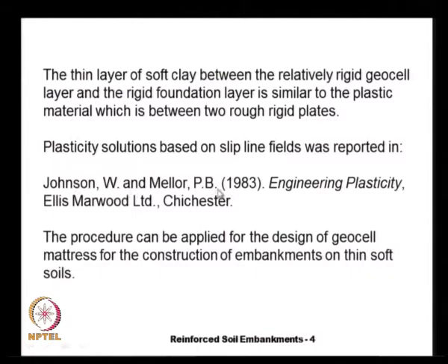Johnson and Mellor in 1983 in their book on engineering plasticity, who derived the slip line fields for deriving the bearing capacity, or the bearing pressure, the maximum pressure that we can apply on the platens. And this procedure can be applied for the design of Geocell mattress for the construction of embankments on thin soft soil layers.